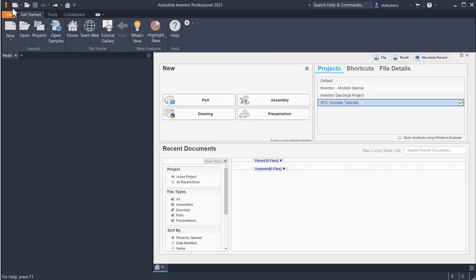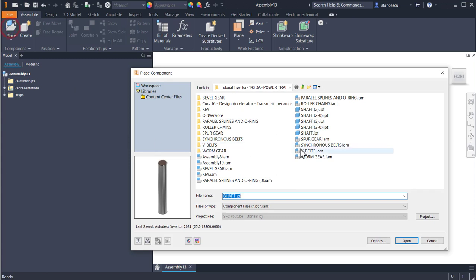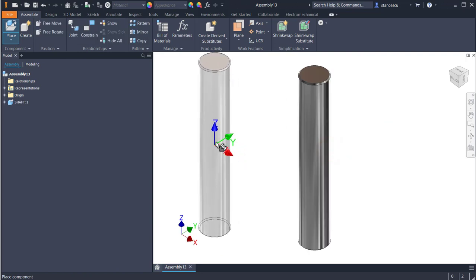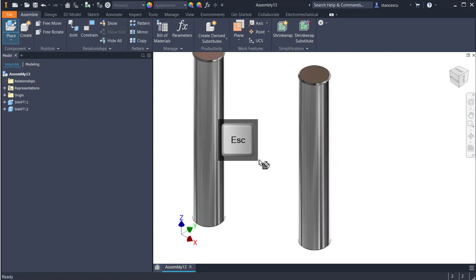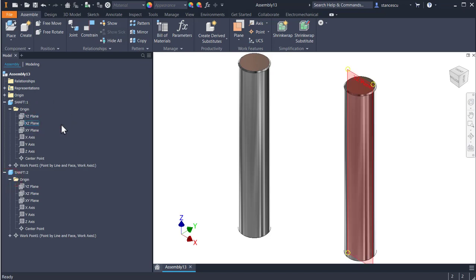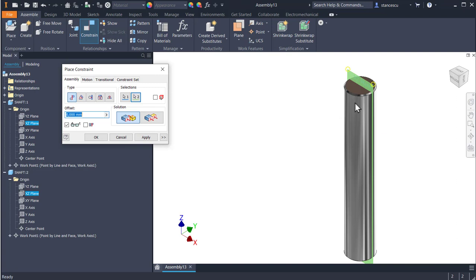Next is bevel gear. We start with the 2 shafts. One is grounded at origin, and the other is near it. We apply constraints between the work entities. The first is XZ, coincident with XZ. They are overlapped, no problem.